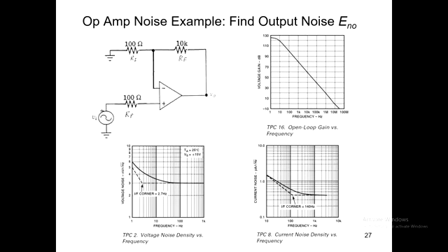No, because the gain is dependent on these resistors. Closed loop gain. But it's giving us the gain here. Surely that's the voltage gain of that, not that with the resistor. We're talking about the amplifier. Oh, that's not voltage gain. That's the voltage gain of the op amp itself, the open loop gain, in other words. Okay. Right. Well, I didn't make that clear, but this is what you get from a manufacturer, typical. Yeah, that makes more sense. So what you actually did was you got the overall gain of this, correct.